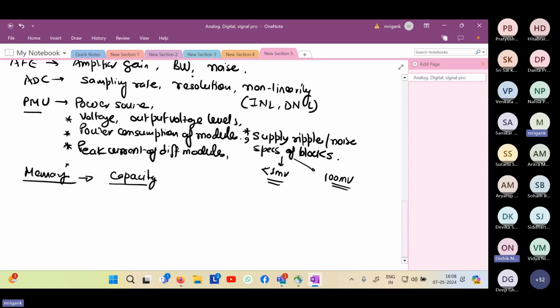Which things will tell you the capacity of the memory? The type of processing that we are planning to do. The number of bits, the resolution of the ADC, the number of bits it will store, will also determine the memory capacity. Okay, that is one partial answer. The ADC resolution, how many bits you are using, partially. What else?